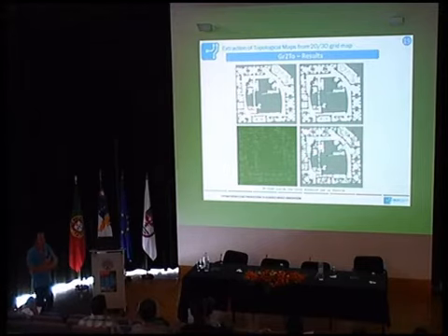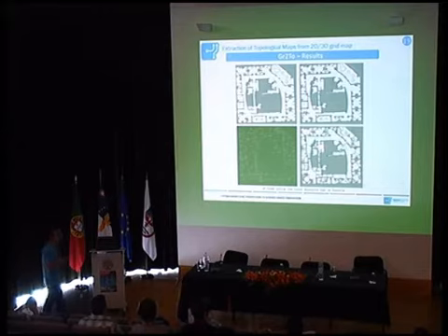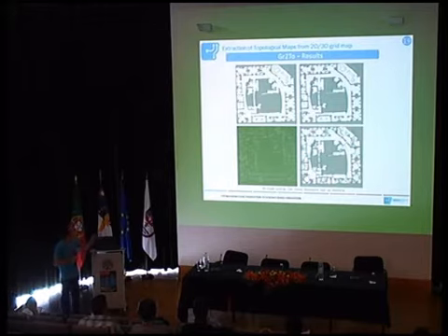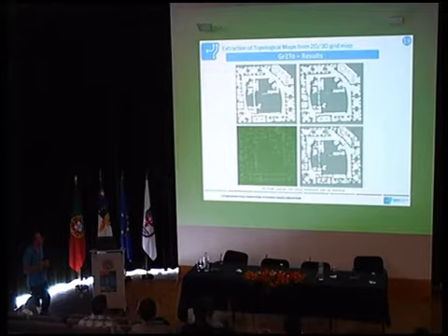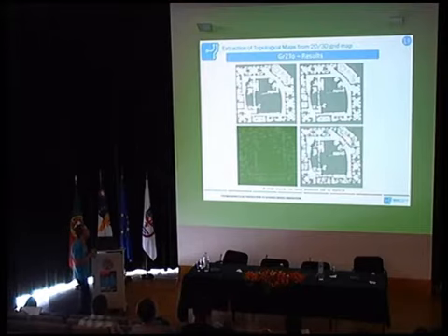Afterwards, I tested this in another scenario, a well-known occupation grid map obtained using DP SLAM. Here you can see on the top the original map. On the left, at the top, we have trouble detecting the doors because they are not so usual and do not have the common size.